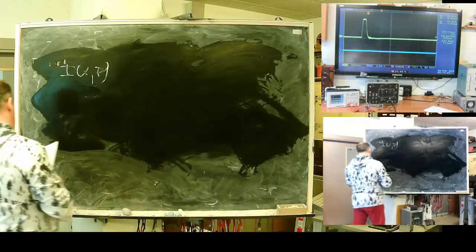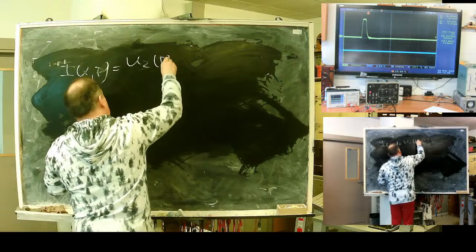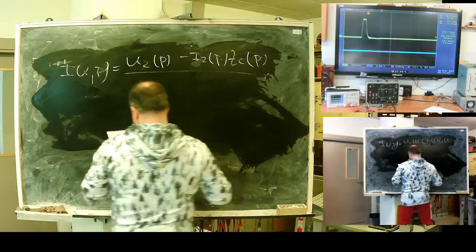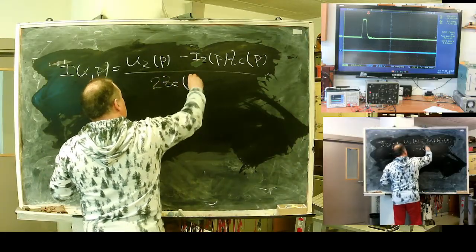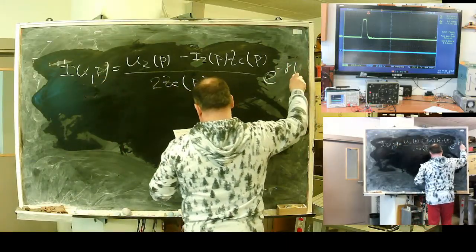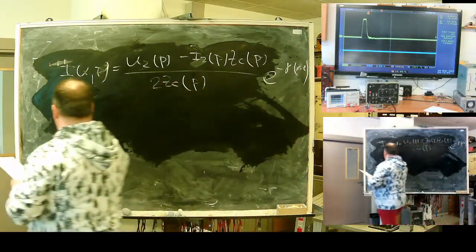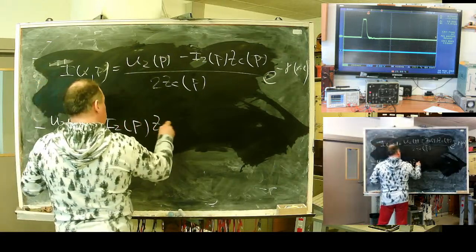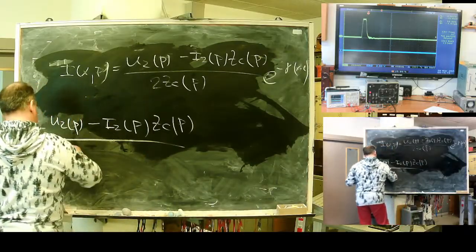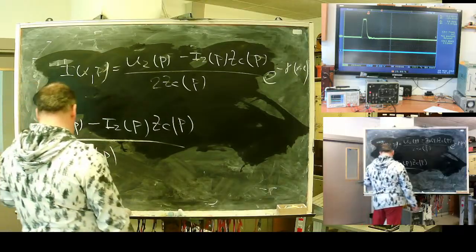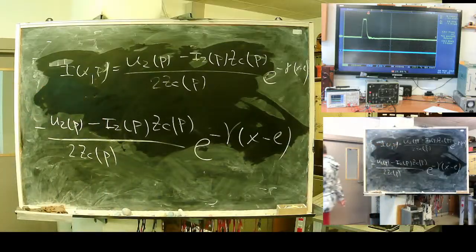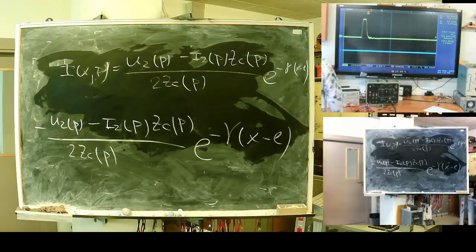Equation number 2 is current in the line. It will be receiving end voltage plus receiving end current, characteristic wave resistance here, e to the power minus gamma x minus L, minus voltage minus current multiplied by wave resistance, divided by double wave resistance, e to the power gamma propagation factor minus L. To simplify notation, hyperbolic functions are used.